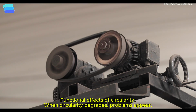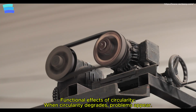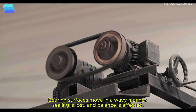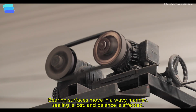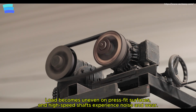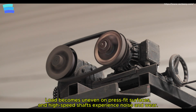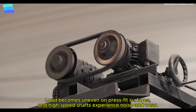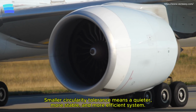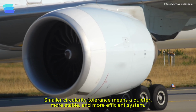Functional effects of circularity. When circularity degrades, the following problems appear. Bearing surfaces move in a wavy manner, vibration increases. Sealing is lost. Balance is disturbed in rotating systems. Load distribution becomes uneven on press-fit surfaces. Noise and wear increase on high-speed shafts. The smaller the circularity tolerance, the quieter, more stable, and more efficient the system will run.